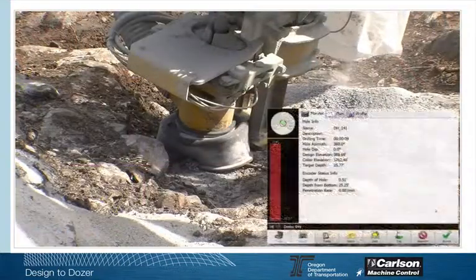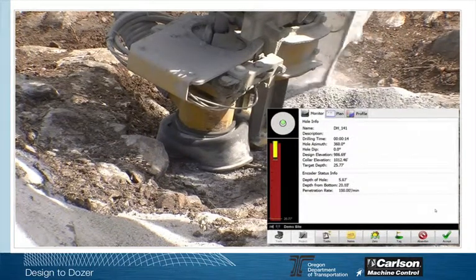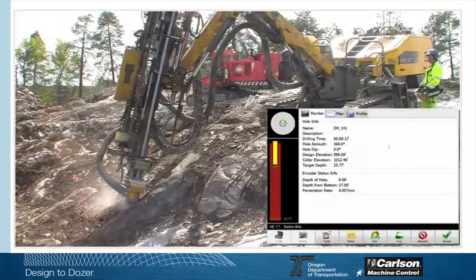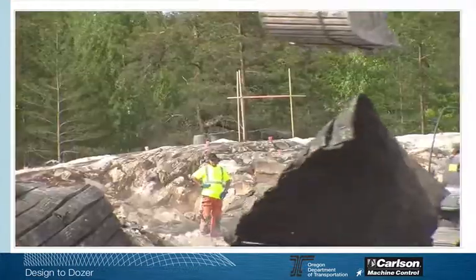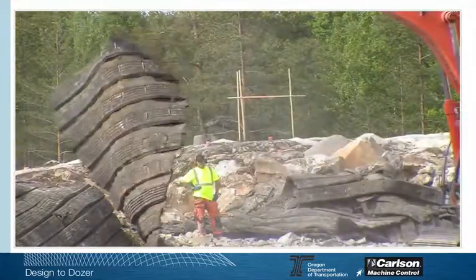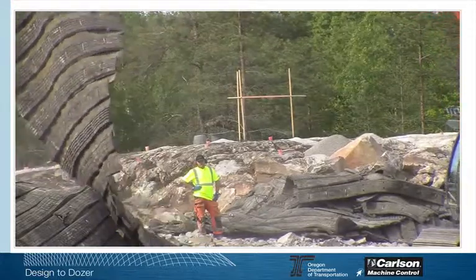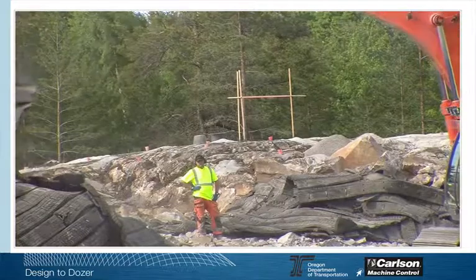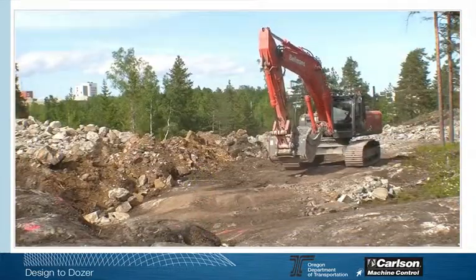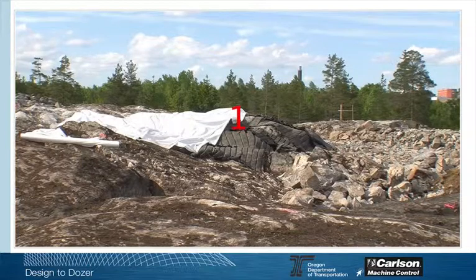Once the drill is placed, then the software can monitor the depth with the encoders. So there are axial sensors on the body, on the mast. There's RTK GPS on top of the mast. There's heading. All the sensors come together, monitoring articulation, and then the application software interacts with the operator. Here they're placing tires and canopy across the blast area to help reduce fly rock. They're removing all of the machines, clearing the area for the blast.